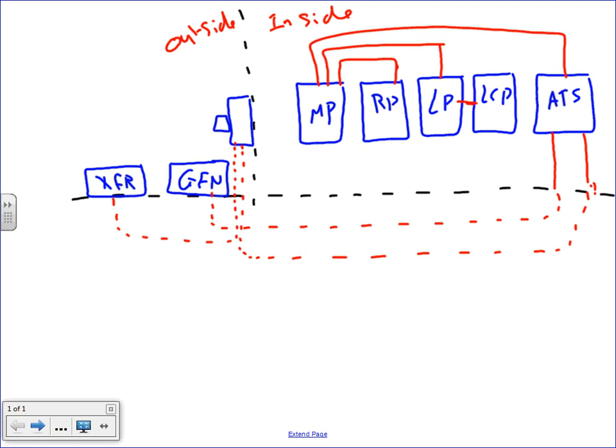I'm going to have an auto transfer switch. The way we're designing it, we're bringing generator power into the auto transfer switch and utility power into the auto transfer switch. So if we lose power, it will switch us directly into the generator. And then we're dumping this power into the main panel. From the main panel, we're feeding the three panels that we have. Any questions, guys, about this?